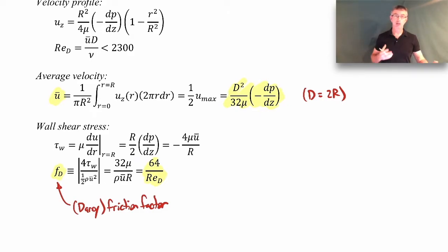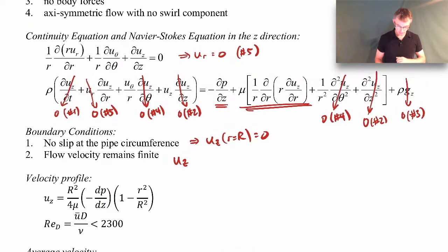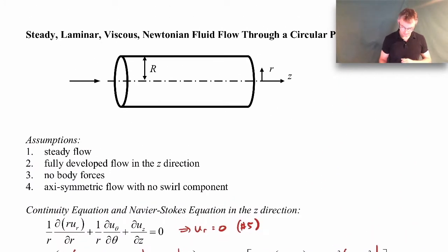Now, I'm telling you all of this, going back through this, because I'm ultimately trying to get back to the head loss term. And remember that the head loss term is related to energy losses due to viscous effects. It's really the reason why we have to have a pressure gradient, like in this particular flow. Let me just go back to the picture. There's a pressure gradient here, a dp/dz that is less than 0.